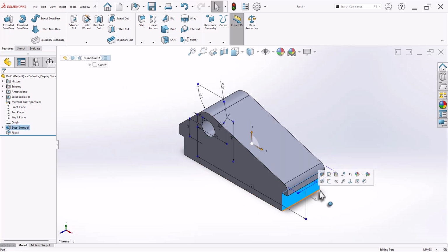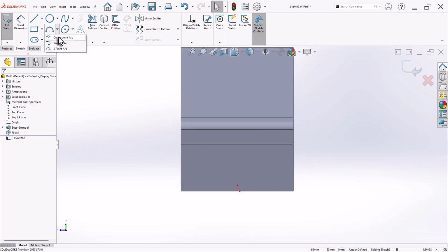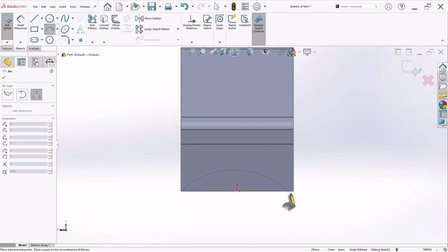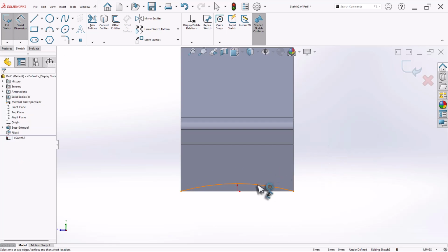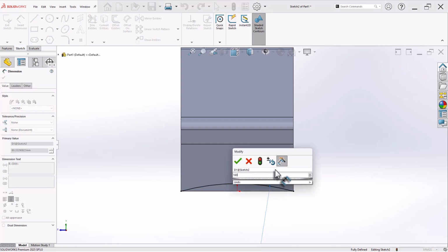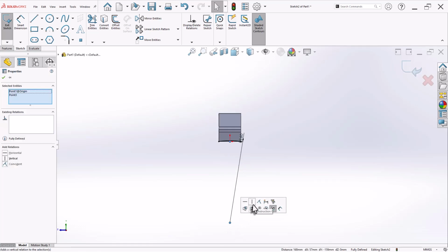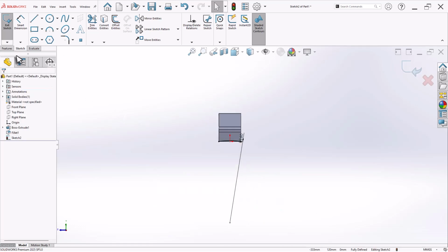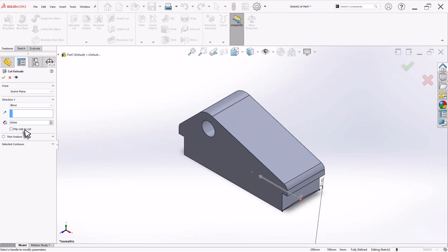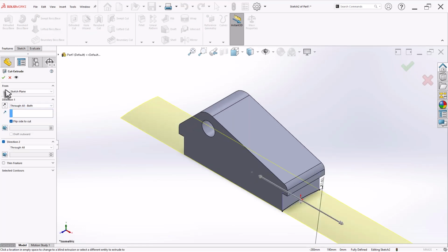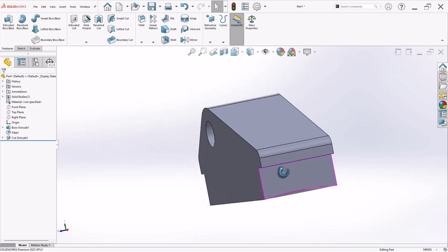Now let's have a circular cut over here. So 3-point arc whose radius is 160. Also make sure that its centers align. Now let's add the cut features. Now let's flip side and through all. So we have the circular cut.